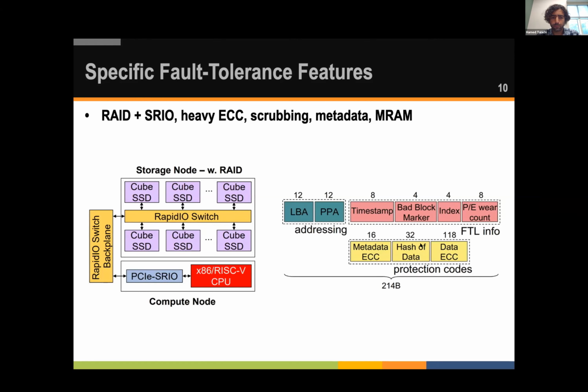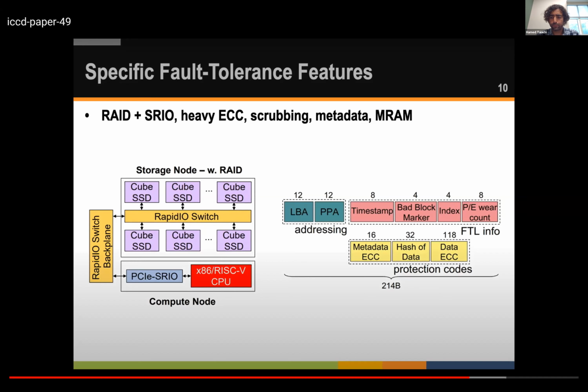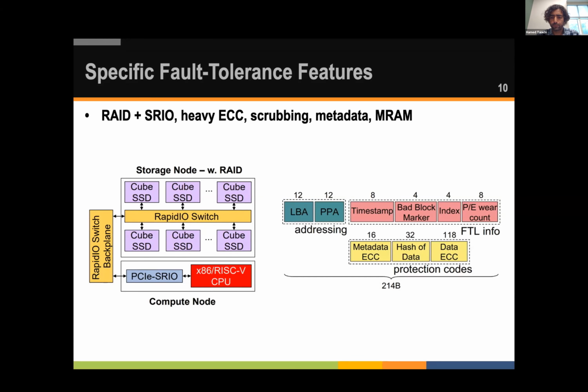We also propose a specific metadata layout. Inside, we store information necessary to rebuild the FTL logical block map and related data structures at startup. It is also used to store other metrics such as program erase cycles. The address metadata is used by the controller to validate page reads and the address translation table. The timestamp inside the metadata is useful for scrubbing validation and identification, and the data hash serves as additional verification